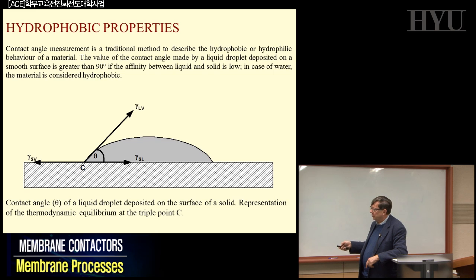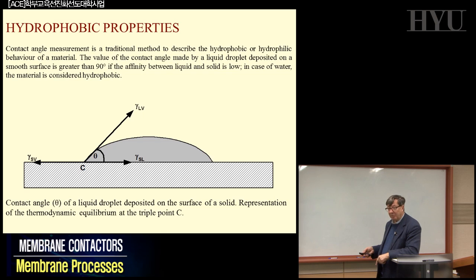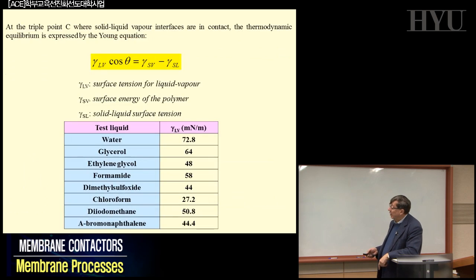For understanding what is happening, this is the contact angle that we have to measure. We want to have these droplets basically not absorbed in the material, but totally rejected. This angle here is not good enough. That is more hydrophilic. This means the liquid is dispersed and absorbed in the material. Hydrophobic means that we have nice droplets on the membrane surface here.